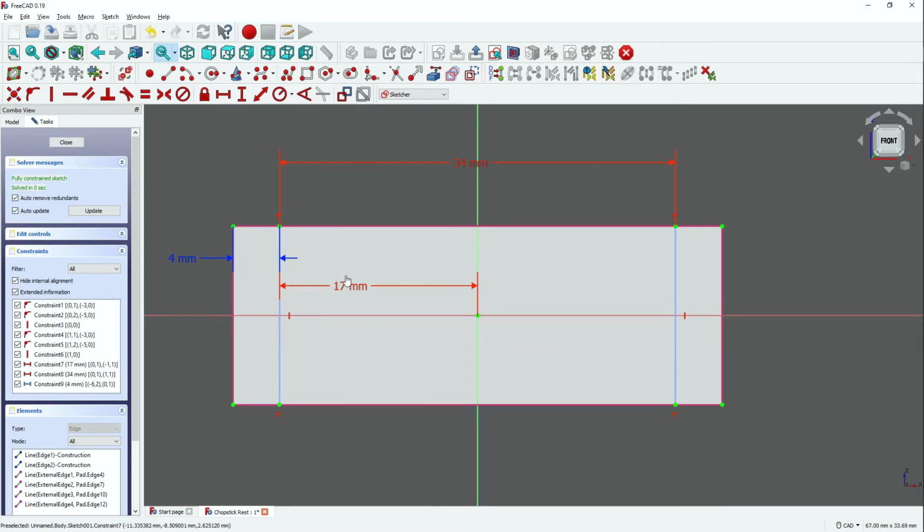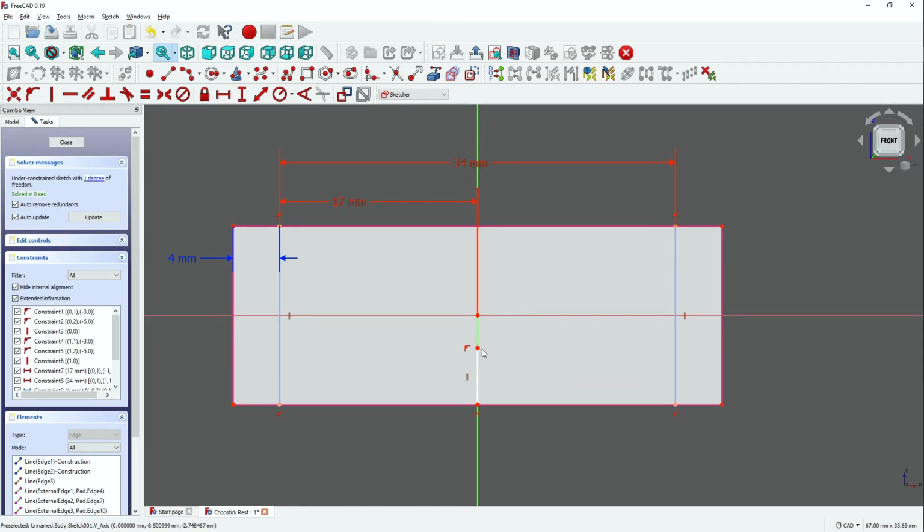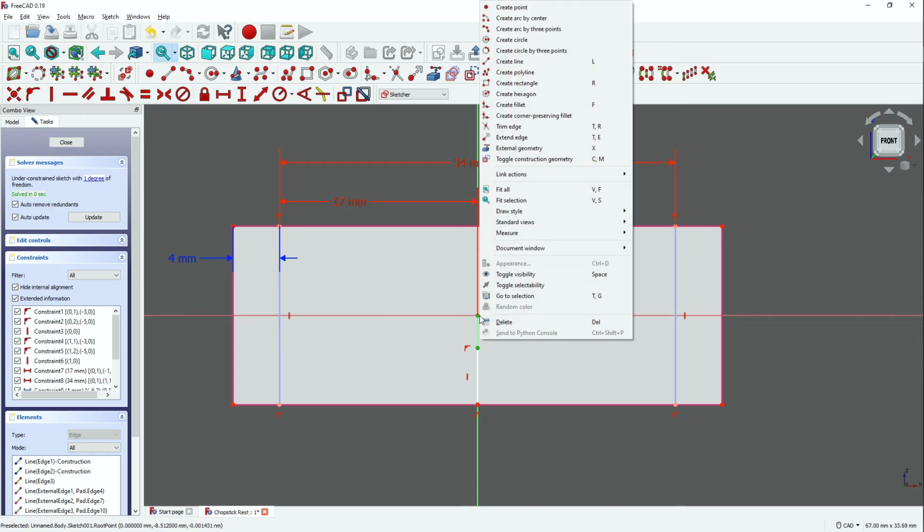So we're going to draw an arc now. From here to there. Oop, that was center point. We want just an endpoint. Clicky, click. And then right. I don't want it to be attached to there. So I'm going to actually draw another line. From here to here. And I want this to be vertically under it.